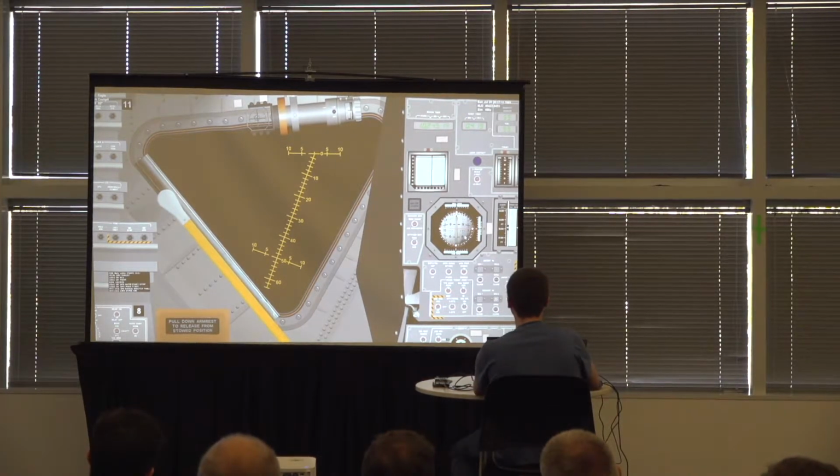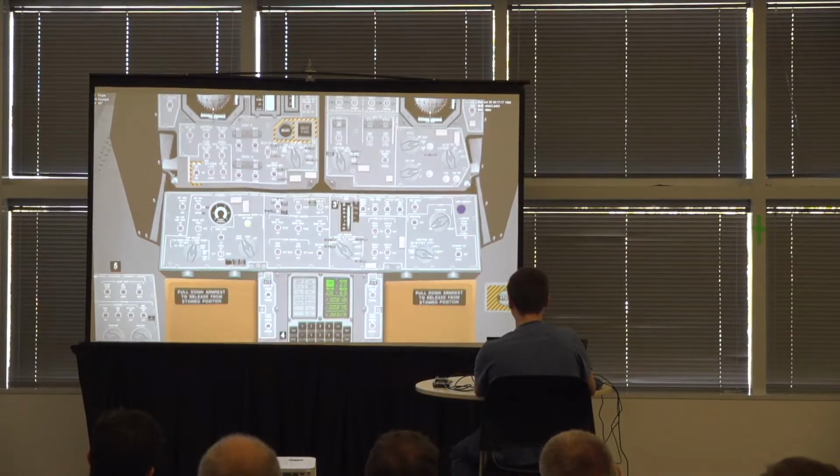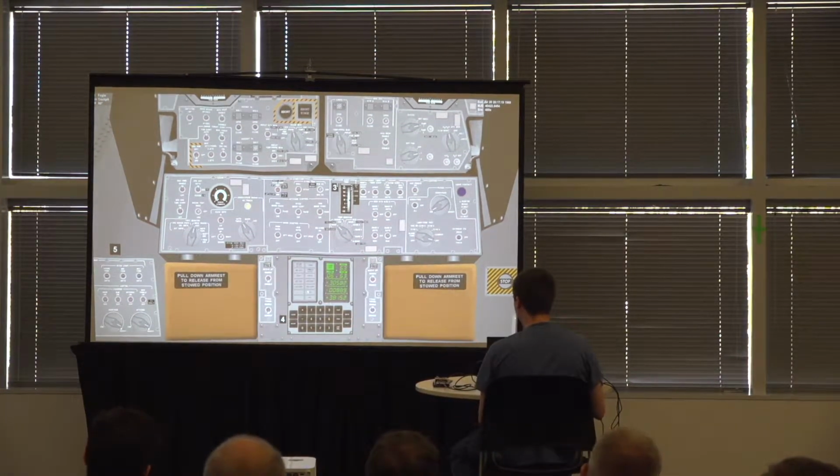Okay, and now if I look down at my DSKY, the altitude light has gone off, which means that we've gotten a lock on the surface. So if I do verb 16, which is display 3 decimal values, noun 68, this display has in the bottom row a very important number called the delta H.